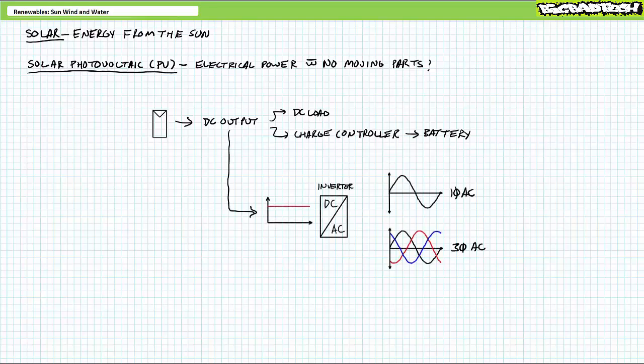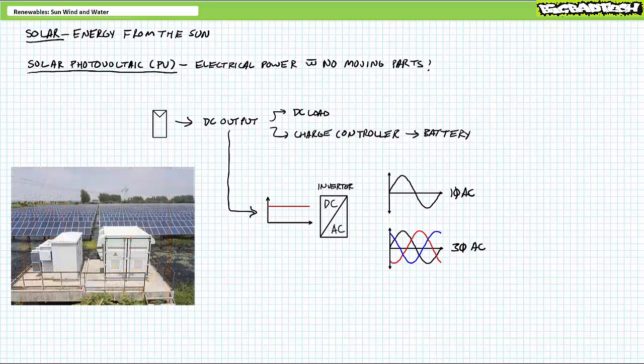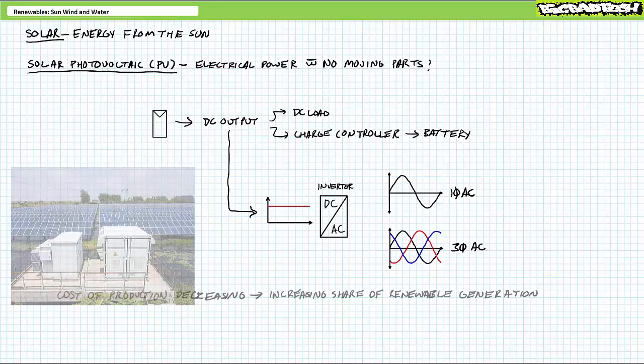However, certain accessory components are necessary to produce grid-compliant AC, principal among them being an inverter. An inverter is a power electronics device that converts the DC input of a PV array and inverts it into grid-compliant AC with the correct magnitude, frequency, and phase shift suitable for export. Smaller residential inverters produce single-phase AC, whereas larger industrial inverters produce industrial three-phase AC.